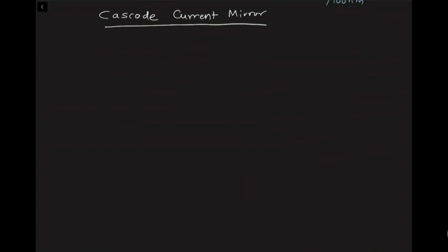All right. So let's move on to the next current mirror. So we learned about the simple current mirror and how you size the devices when you would like to get scaled copies of the current mirrors. Now the next current mirror I'm going to teach you about is called the Cascode current mirror. In the Cascode current mirror, we already learned what Cascode means. You have one device, and on top of that you put another device with a bias voltage and keep everything in saturation, and we call that configuration a Cascode transistor.